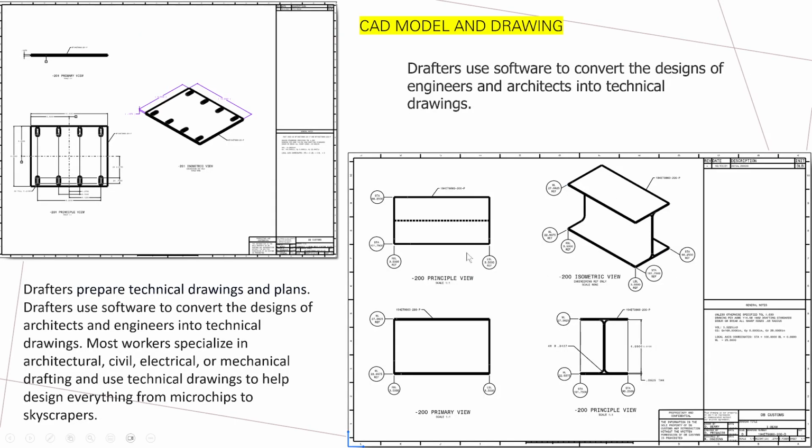This over here on the bottom right is the I-beam, and up here on the top left is the top plate of the I-beam or I-beam mold fixture. And you can see we learn ANSI ASME type drawings, applying ANSI ASME type dimensions versus the I-beam. We also learned how to dimension in XYZ coordinates. In this example, we dimensioned using station line, buttock line, and water line.